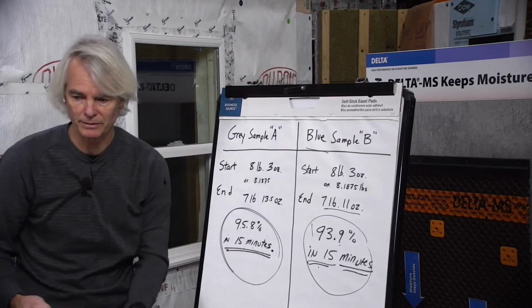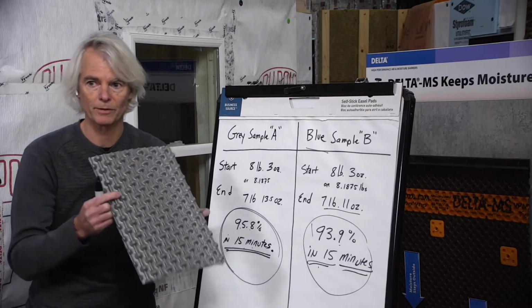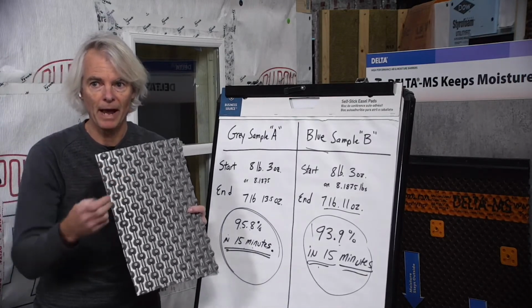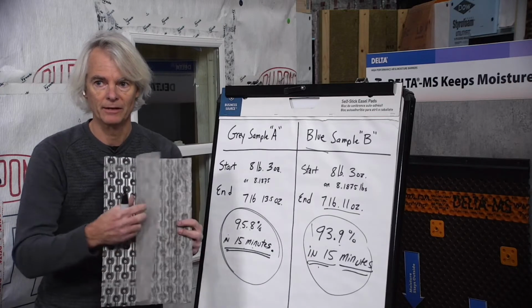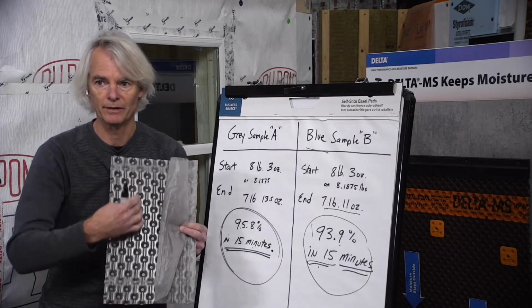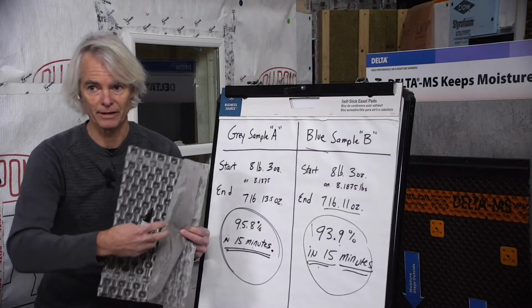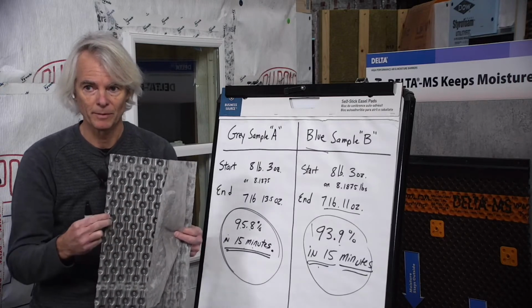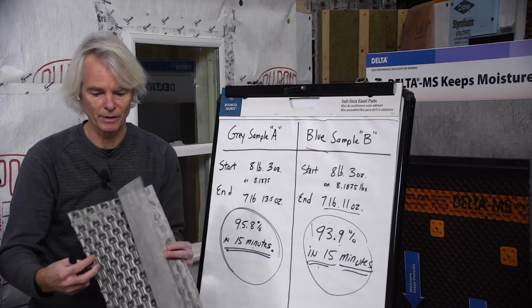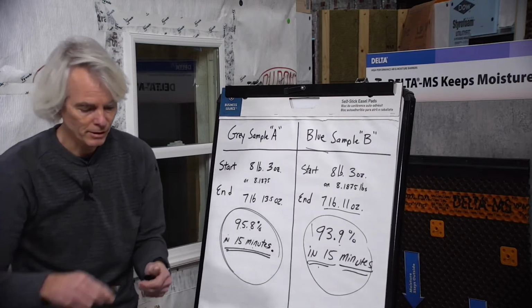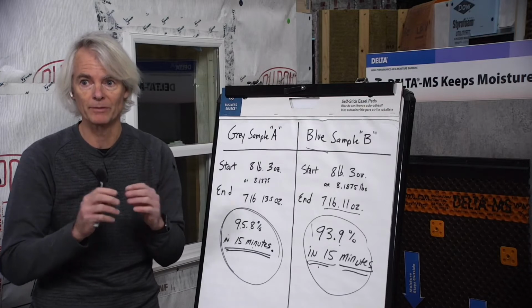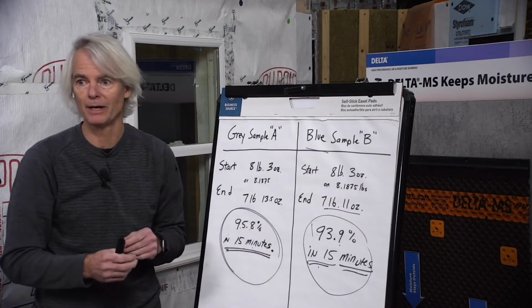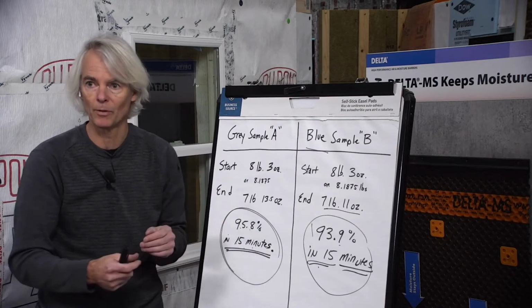And I do want to remind us that the drainage surface we were looking at is the drainage surface on the back, and to point out that there was a drainage surface we have yet to test, the speed at which we're able to drain down these vertical channels on the front. And that's one of the magic parts about this particular membrane product. It's impervious. So it's a pretty fun test, though. As we can see, the main takeaway here is that rain screens work in rapid drainage. That's rapid drainage in both examples, just one even more rapidly.